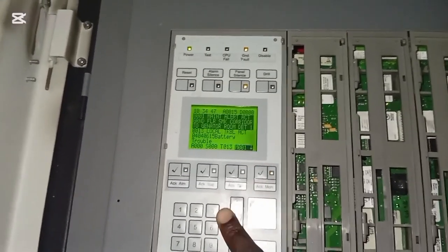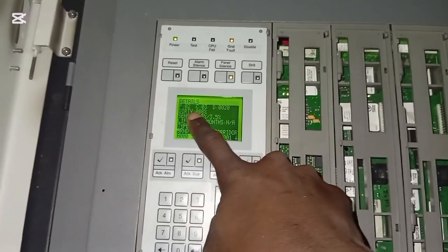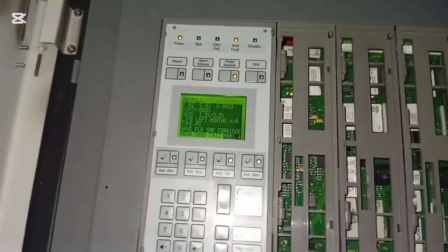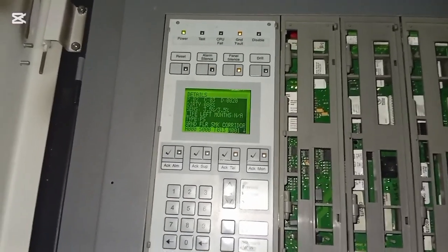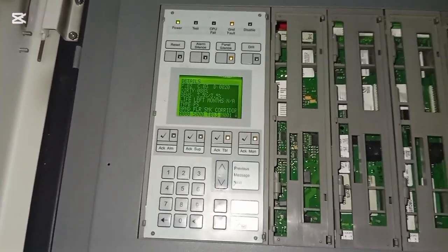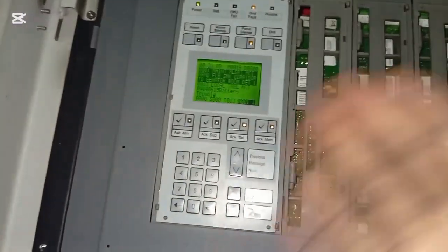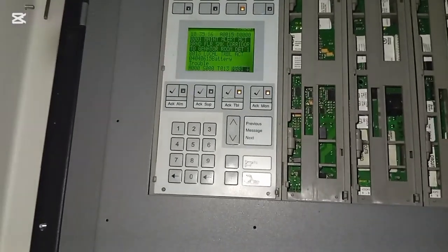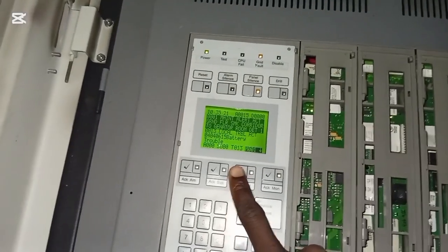Another easy one is this dirty head. You can see this detector is 88% dirty. That means that when it reaches 100%, this detector will send alarms. That alarm will not be the detector detecting smoke, it will be a false alarm. So this false alarm is caused by detectors being dirty. To avoid this, you should arrange to clean those detectors so that you remove dust from them, to avoid false alarms.